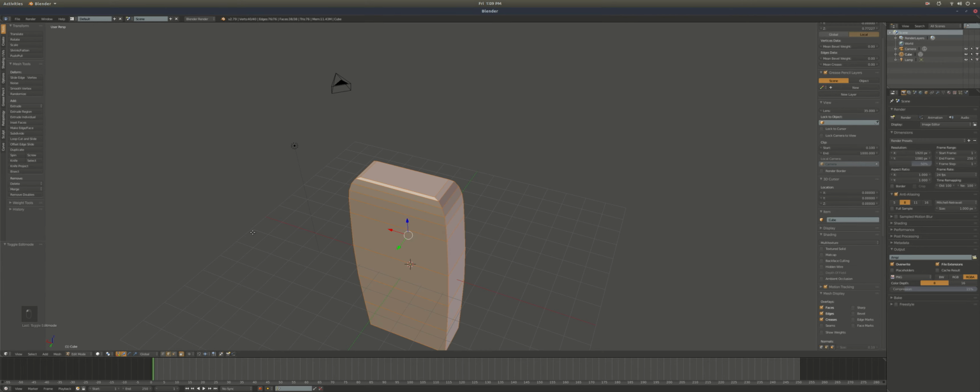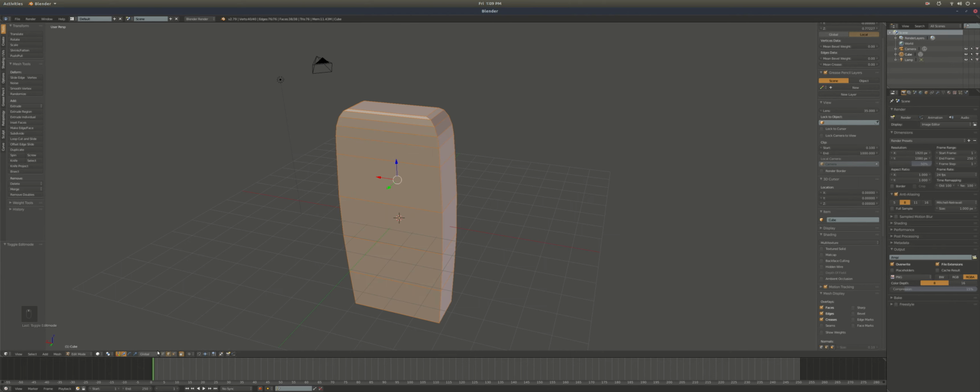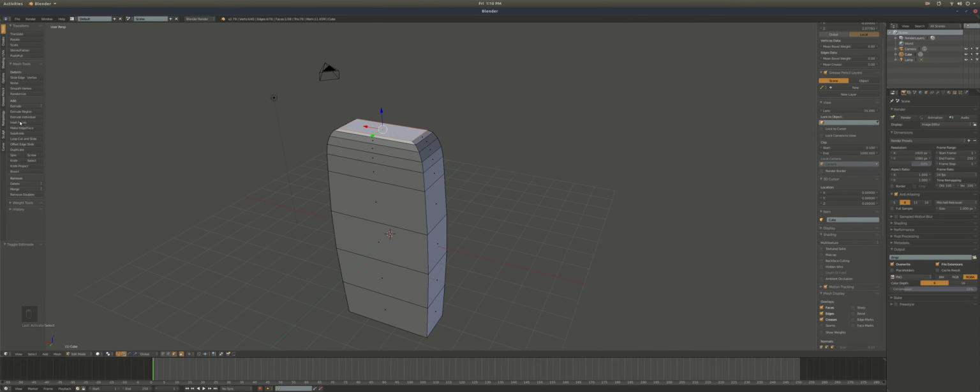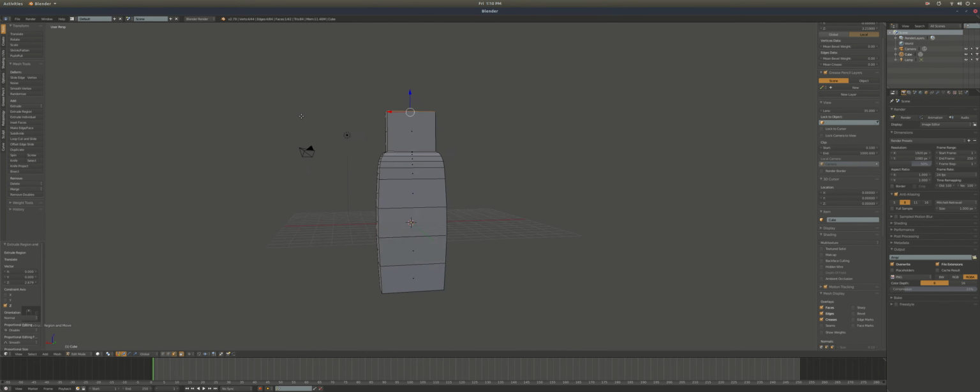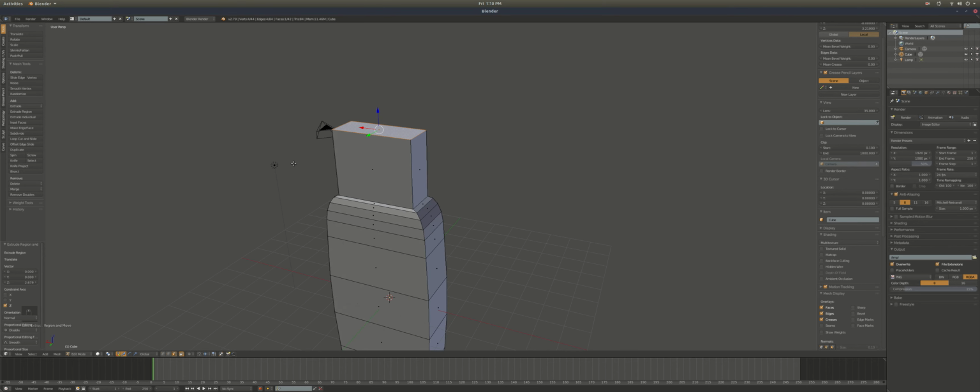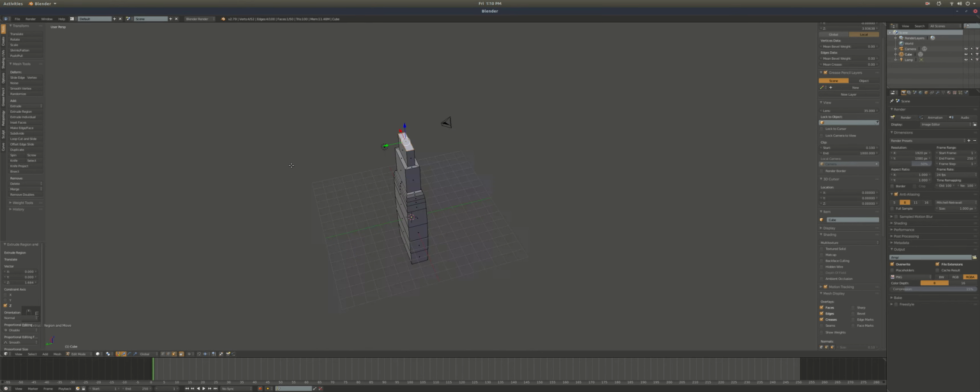So if you go back into edit mode, which you have to change if you want to start modifying the object again, and you select a face, up here you have all these extrude options, but you can just hit E. And E is going to be very simple. Simple way to extrude. Another good one is I, which is inset. And hit E again, and you can begin extruding. All these options are up here on your toolbar on the left, but hotkeys make it much easier, and so do the pie menus. The pie menus really make it simple.